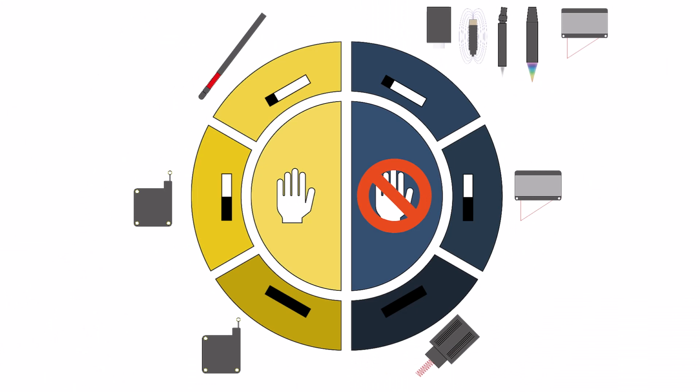Of course, you might not always find a sensor with your desired offset, but you should rather go for a larger offset than for a larger measuring range. After deciding between contact and non-contact sensors and selecting a measuring range, you can see that you already narrowed down your choices quite well. However, for the non-contact short range category, we still have quite a few options. And this brings me to the third decision criteria.